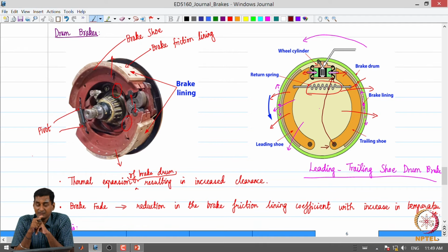Of course, the advantage is that we get more brake force output for the same input because the brake factors increase, and essentially from a performance viewpoint it is good. However, what is the trade off? We see that to generate an actuation force at the bottom, we need to have a similar actuation mechanism at the bottom, we need to duplicate it at the bottom, right.